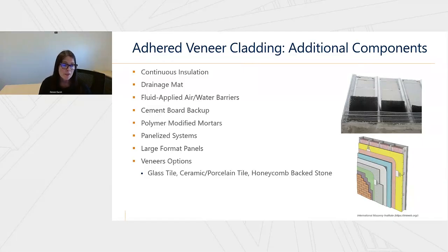We also have different types of backup, one of them being the cement board. Sometimes we'll see this with the use of continuous insulation because we have that continuous insulation that's inboard, and then we need another backup system, and cement board can function as that backup for attaching our adhesive system.